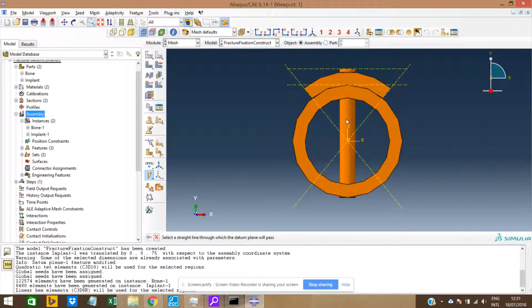Okay, next. And you're gonna have to trust me on this because I did a lot of trial and error. Next, you also want to do another plane that is offset from the YZ plane, and YZ 0, so it's just actually the YZ plane. Another offset from the YZ of 3.